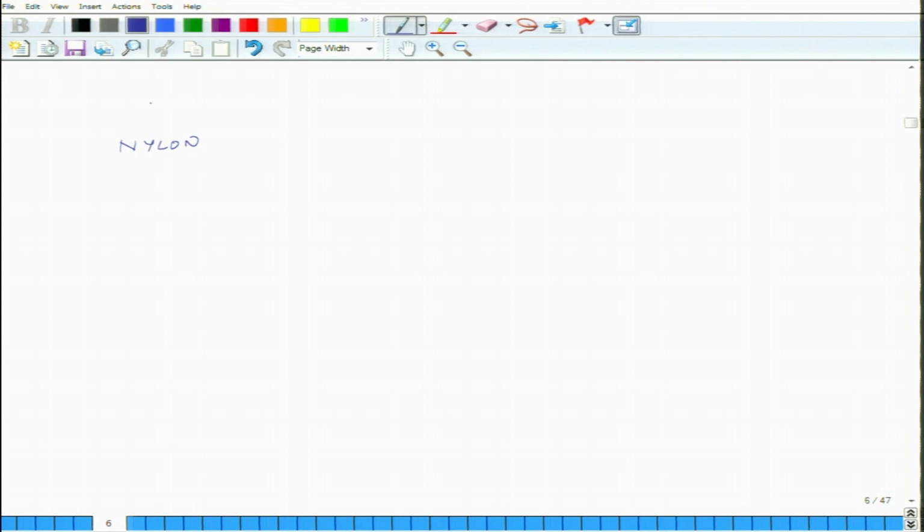So this is the material, and this is rho semi-crystalline. First we will specify the density of the semi-crystalline version and then of the amorphous version. For instance, you have nylon, its semi-crystalline could be as high as 1.24, but amorphous version 1.08. So, it is significantly different. Okay. PET, this is another thermoplastic, this could be as high as 1.5 and this is 1.33.